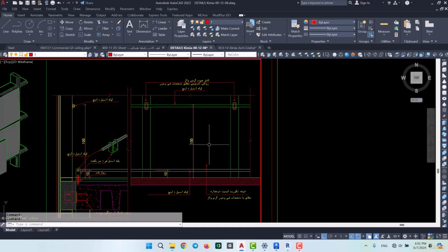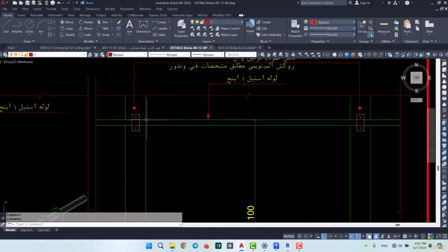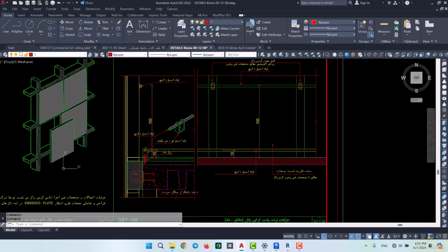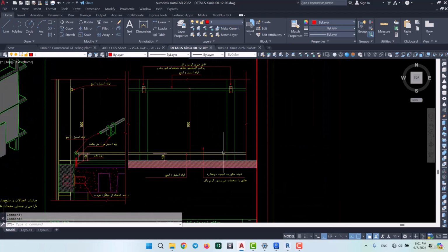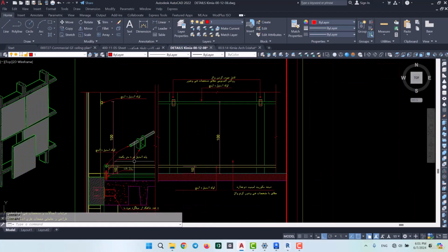And as for the middle part here which says glass, that's for the curtain wall, then we've got the mullions on the sides, and behind those is where the railing will be placed. We can see from here that the railing is connected to the mullions, and maybe it would be better to check that out in the section. So up to here, we don't need to really pay attention to all the details. It is enough that so far we know we need to draw a railing, which is made of 2 steel pipes with 1-inch diameters. Now we know that 1 inch is equal to 2.5 centimeters, which will make the radius of these pipes that we need to draw about 1 centimeter and 25 millimeters.